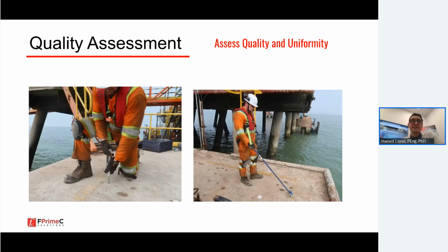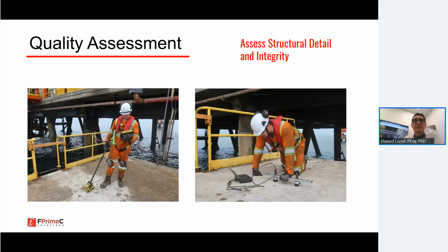Because this is a systematic project, we start at the very beginning, with the very basic tests. It might be disappointing for you to see these being the first steps, but these tests help us focus more advanced technologies on the areas that are required. So a few tests to identify the quality and integrity of the concrete itself, and GPR for identifying the location of rebars and potential delamination.